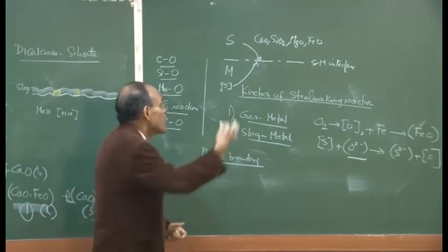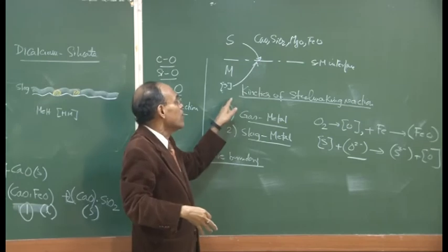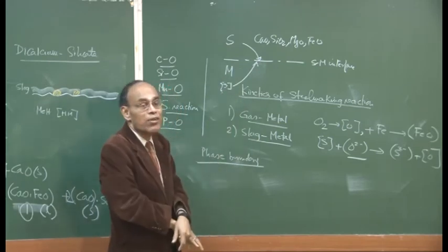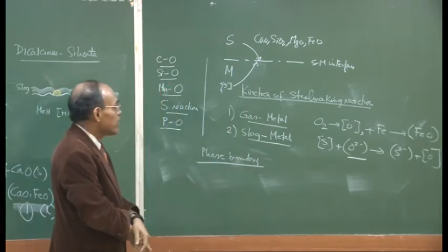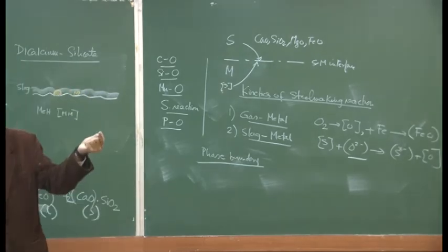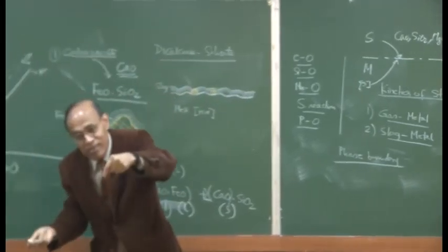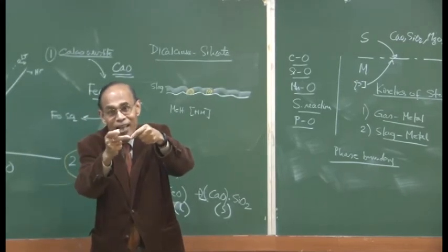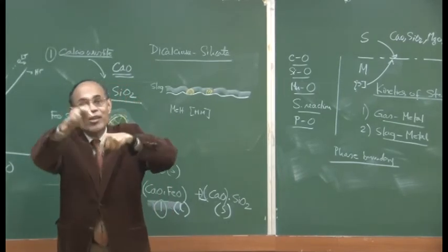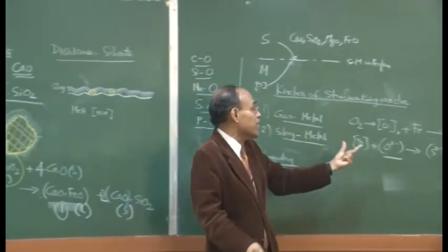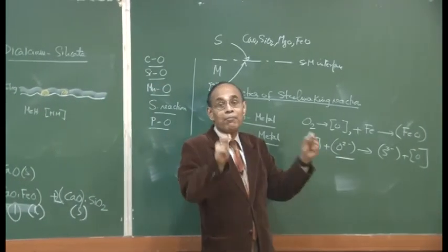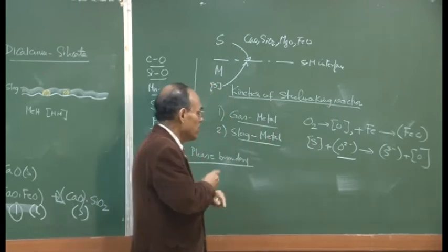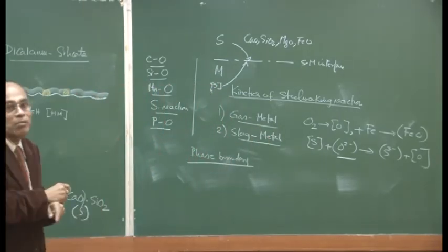So, there needs to be a continuous transfer of sulfur from the bulk of steel to the interface itself. Calcium oxide will transfer from slag to the interface, sulfur will transfer from the bulk of metal to the interface, then they will react, the rearrangement of bonds is going to take place, and then we will see a pure chemical reaction between sulfur and CaO right at the slag-metal interface.